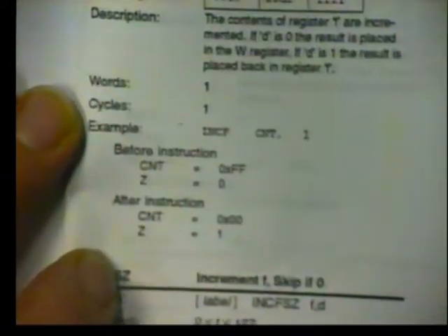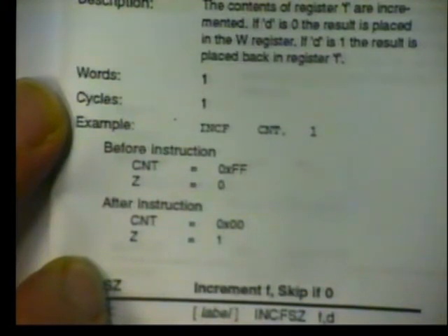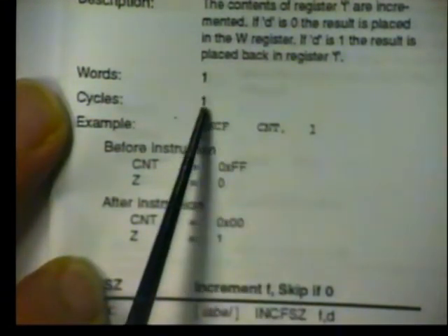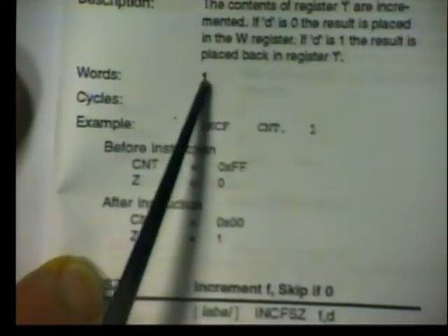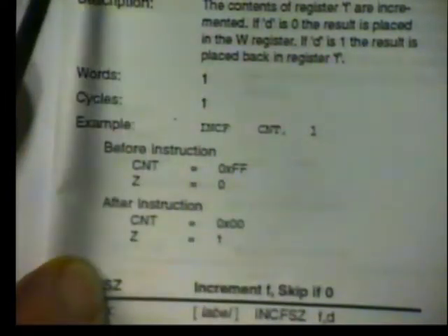When I say quickly as possible, you may have noticed if you go to the data sheet for the PIC processor, I'll just zoom in on any page, any instruction, it doesn't really matter. You will find you always get a line that says cycle time. This tells us how many machine cycles it takes for that instruction, whatever it is, to occur. Why is that? Because part of the job of designing an interrupt service routine is to calculate how long it takes to execute.